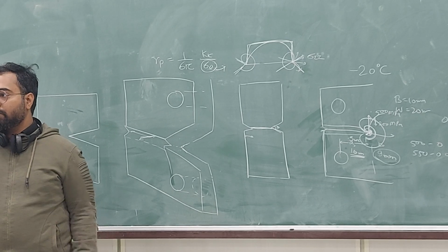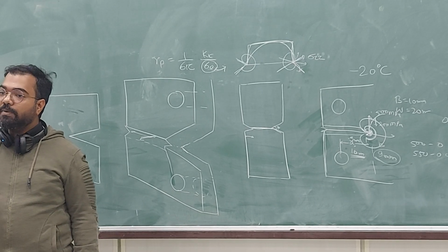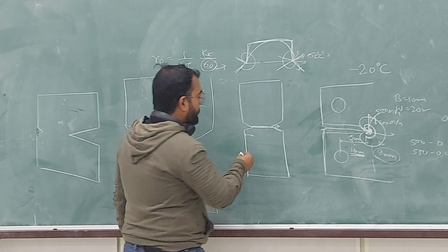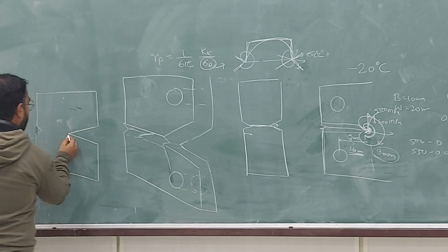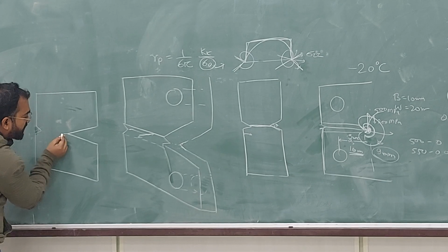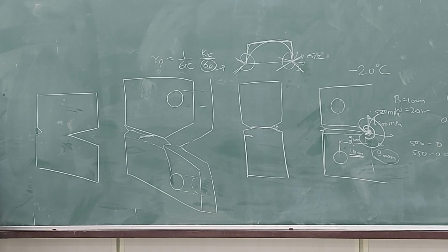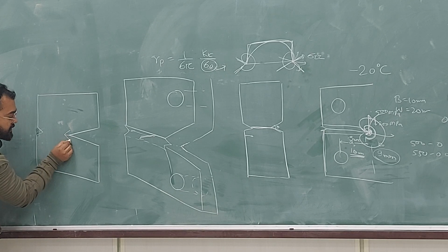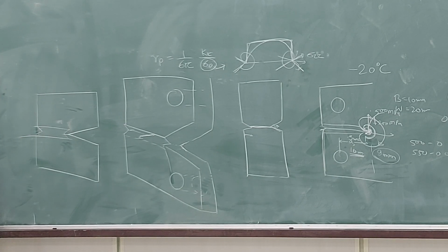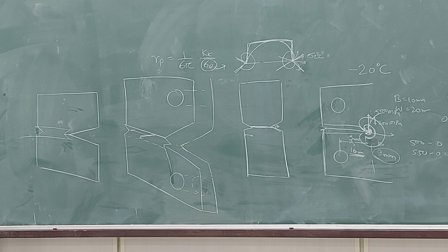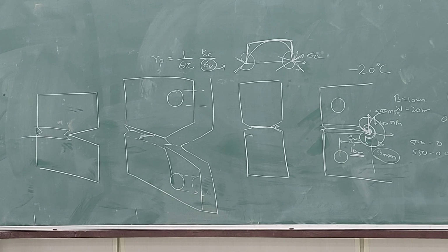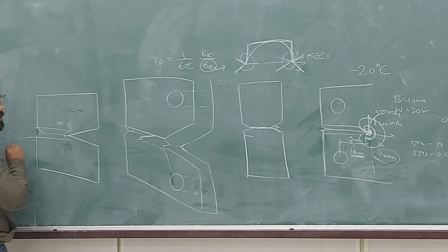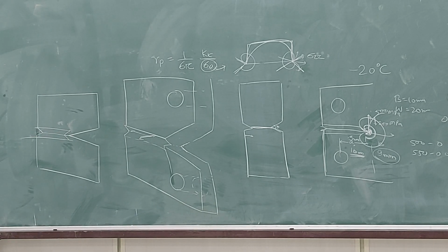Okay, so first you are supposed to make the fatigue pre-crack, then you are supposed to do the side grooving. So I have this sample, I have made the fatigue pre-cracking, so I can see where the crack is. Okay, so from here I will take theta by 2, and I'll ask some vendor or myself to cut it, so that I ensure that the tip of this side groove lies on that plane of the crack tip.